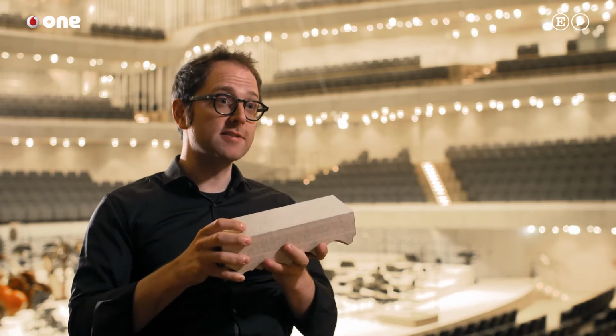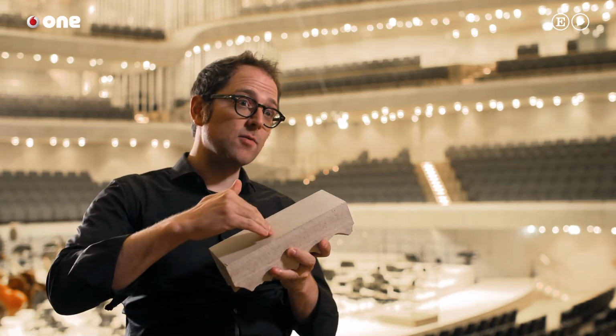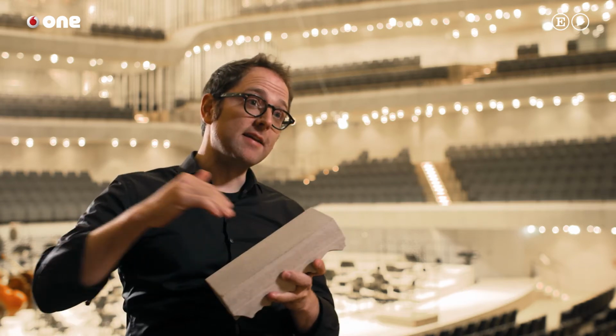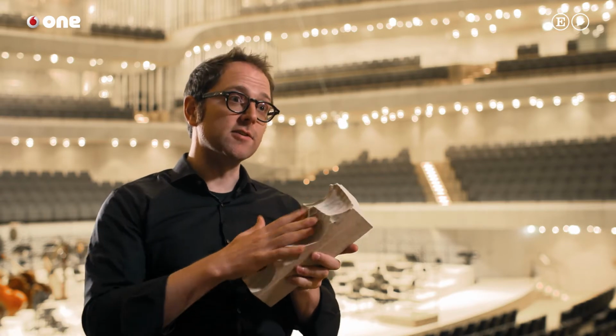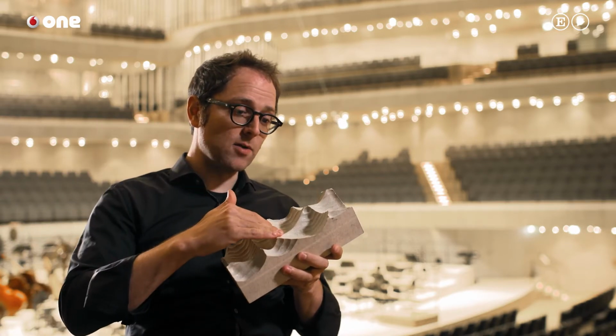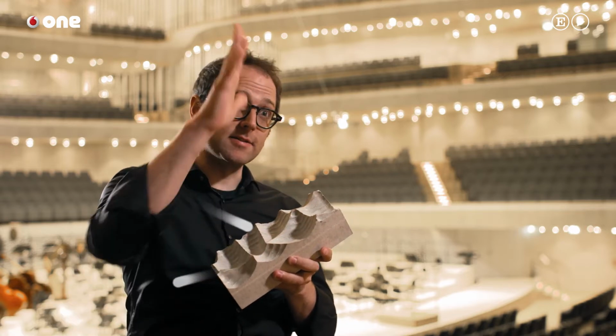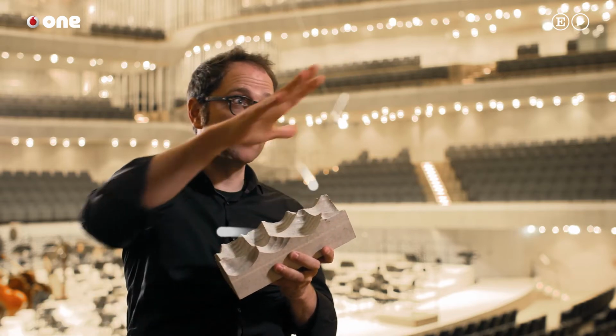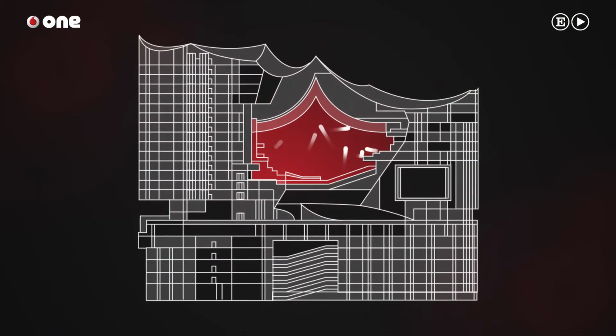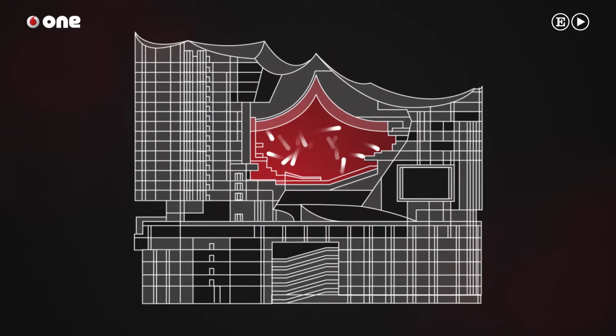The main purpose of the acoustic panels is to scatter the sound. If you take a flat surface, the incoming sound waves are reflected at the same angle that they hit the surface. And that might cause a concentration of sound waves in one area of the concert hall and maybe a scarcity in another. If you take an uneven surface and the sound waves hit the surface, it scatters and diffuses the sound. So it spreads out the sound throughout the concert hall for a more evenly distributed sound diffusion.